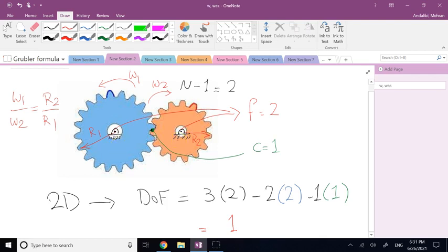We'll talk about it later in machine design videos, but this is called the radius of the pitch circle in a gear, and it's not really from the center all the way to the crest of the tooth, or what we call the addendum radius. So, again, once I know one of them, say omega 1, since this ratio is constant, I can definitely find omega 2. So omega 2 is not independently controlled. It is controlled by omega 1. Okay, so that's the meaning.